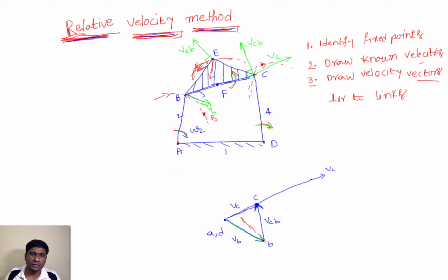So that's why this should be in the downward direction, or otherwise I will write in a green color. This should be in the downward direction from the E. What is this one? This is nothing but V, velocity of the E with respect to point C. So here if you draw a line parallel to the velocity vector EC, then it comes like this.